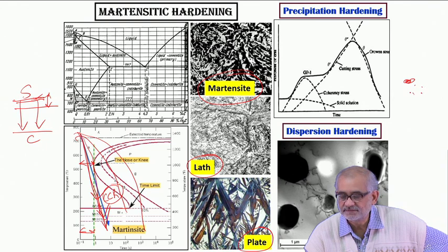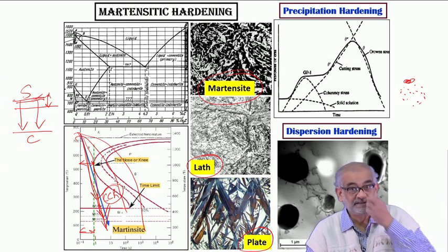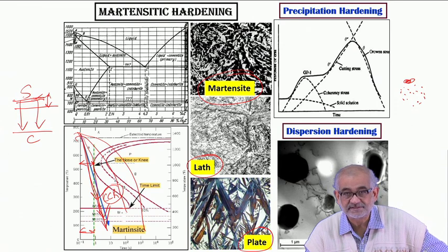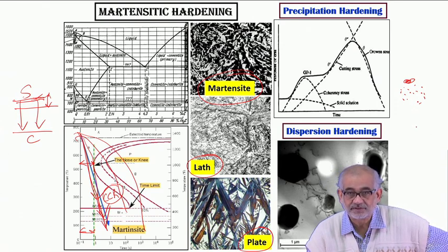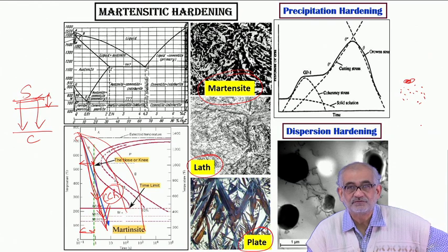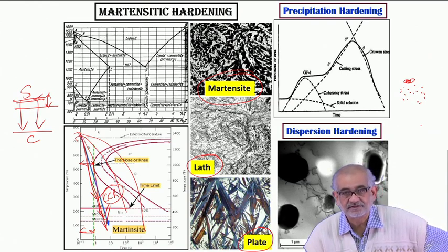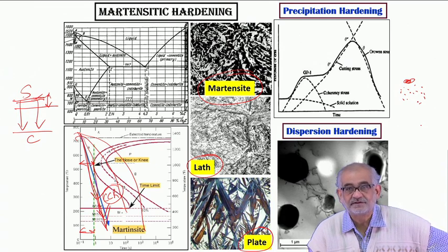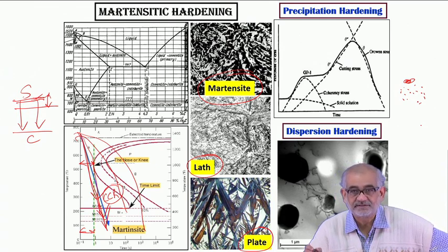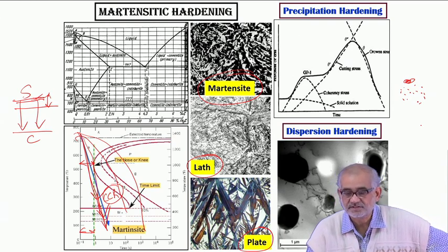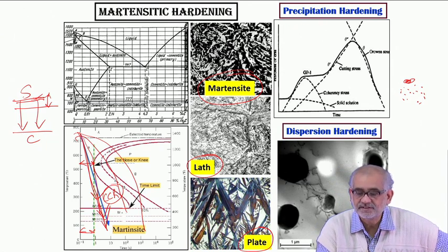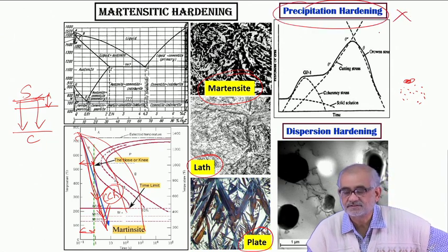So if we have tiny little precipitates formed all over and they are not allowed to grow, then some of these precipitates may maintain very small size, and at the same time the surface will be at least semi-coherent, if not coherent. But coherence is something we don't quite expect in the case of nitride, because the crystal structures are very different from ferrite. So if you have two phases, alpha and beta, with vastly different crystal structures, you don't expect coherency at the matrix. If you don't have coherency, then obviously you don't expect precipitation hardening.